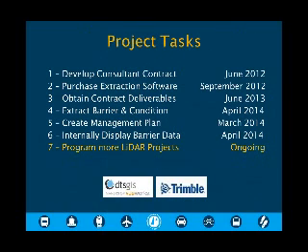These are the tasks broken down by timeline. When I look at this, I was thinking, oh my goodness, this took a while. This was kind of a long project. But there was a couple things here. We wanted to keep the project costs as low as possible. So in this project, we collected mobile imagery throughout the whole Metro District, and then we collected LiDAR just in 3 different locations. And what that did is kept the project costs lower.